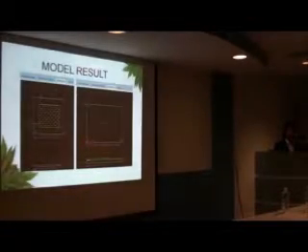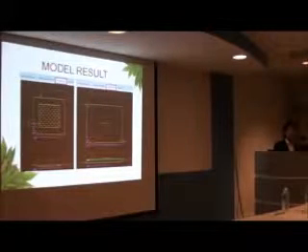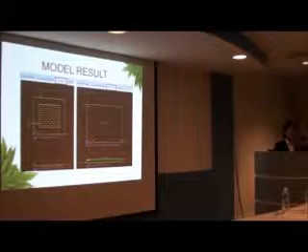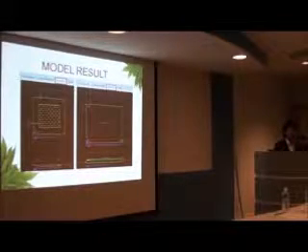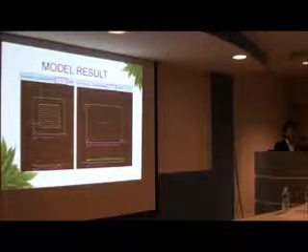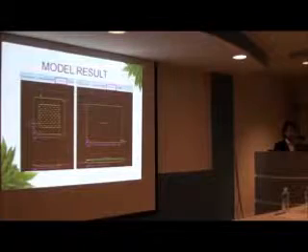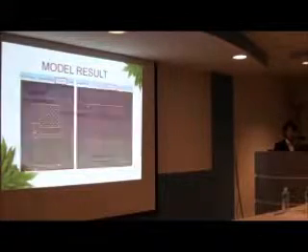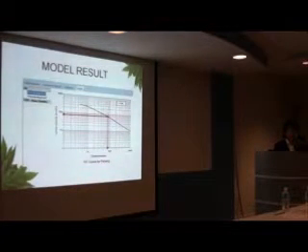And the detailing. The left hand side is an above ground OSD, the right hand side is a below ground OSD. Both detailings are basic, simple detailing. The engineer needs to later touch up based on his or her design specification. And then the last output is the pre-development and post-development IDF graph and the storm duration graph.